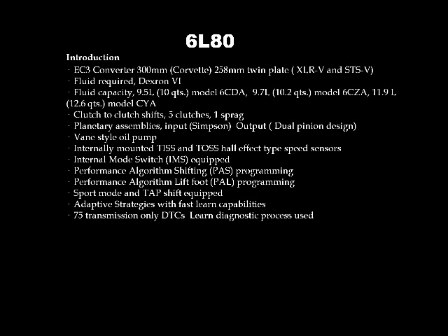Internal mode switch. So we've got obviously no pressure switch like you're used to seeing on some of the other transmissions themselves. We do have pressure switches that are built inside the TECM. There's no external pressure switch on the valve body itself. Instead, they use an IMS like some of the later 4-speed transmissions have used.